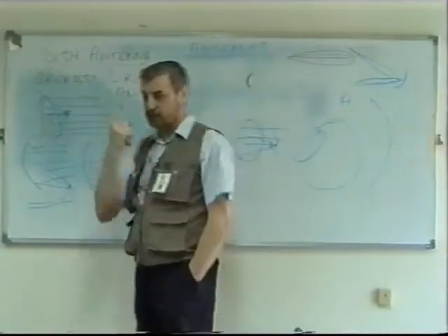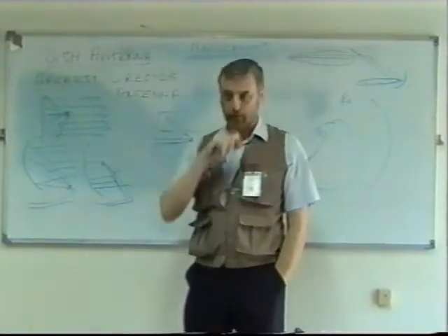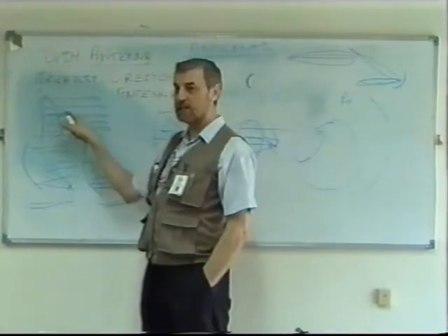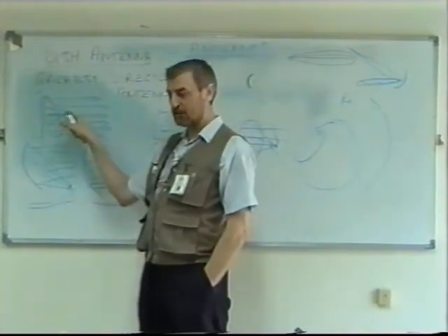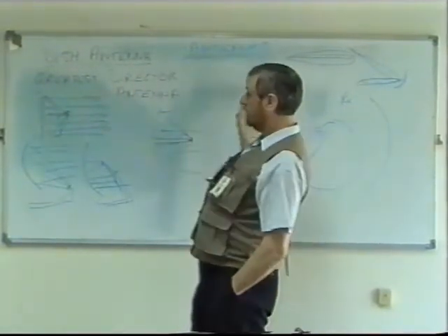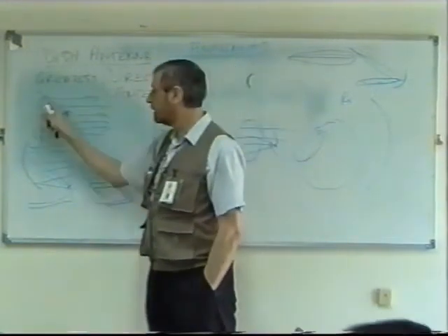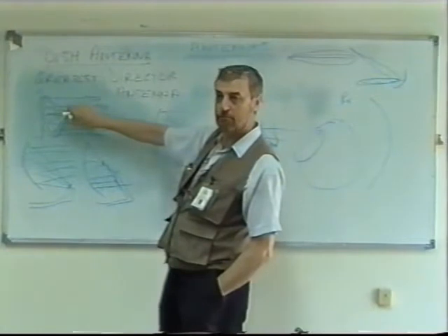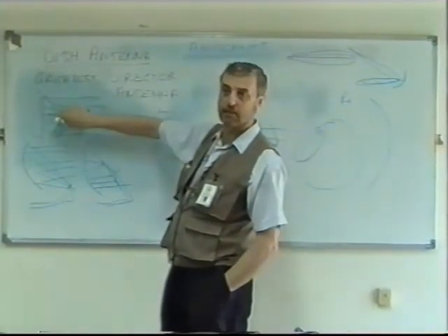Can it be used as receiver and transmitter at the same time? You can. In fact, that's exactly what happens on our point-to-point communication using microwaves. Using the same antenna, we can use it for transmitting and receiving. But what I want you to think about here is using it just for one reason, either as a transmitter or as a receiver, not both. If it's used as a receiver, it receives the radiation from the other side, wherever that is, goes to the reflector, and that concentrates the beam onto the actual antenna, which is here.